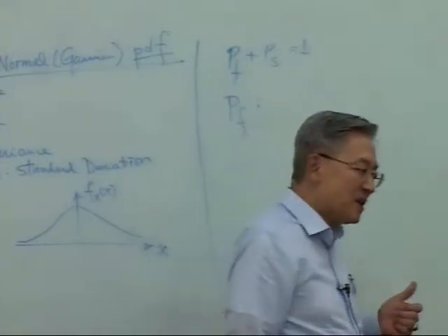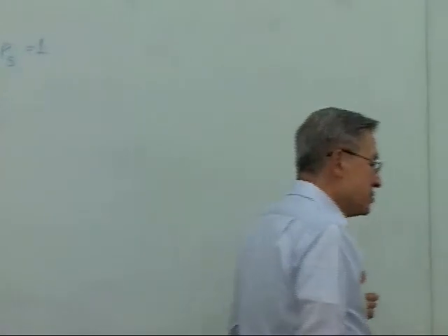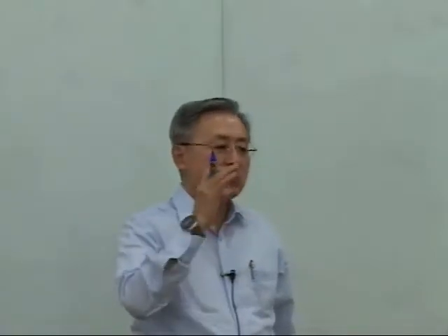When you conduct the deterministic design, you preset the yield stress, 36 kpsi, 36,000 pounds per square inch. Then by applying the actual loading, you want the resulting stresses at any location in the system not to be larger than the yield stress, to avoid any possible permanent set.